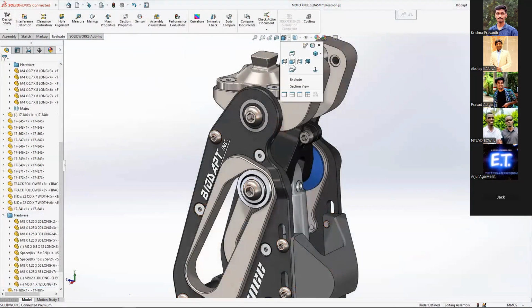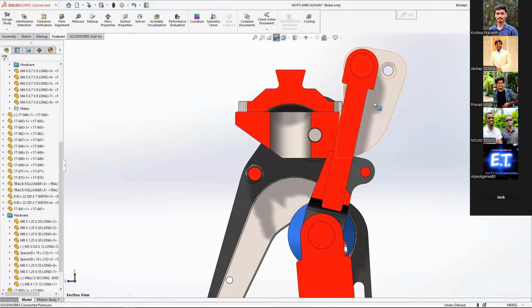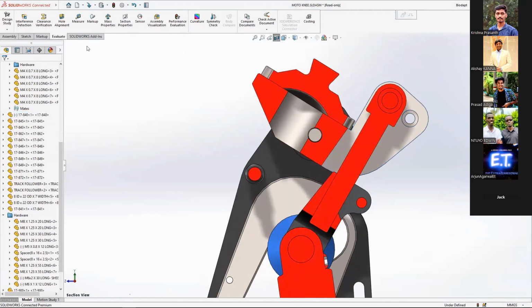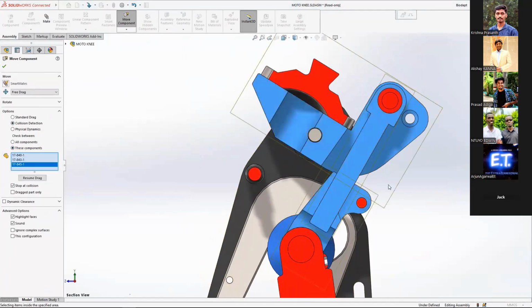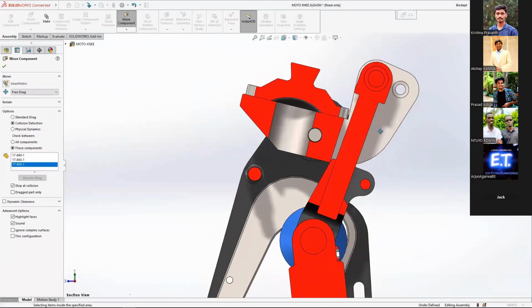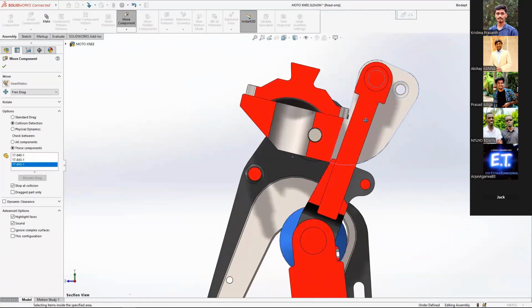So if you remember back to the post in the community, one of the engineers is asked to perform interference and collision detection. One of the great capabilities in SolidWorks is interference detection, or in this case, collision detection. Here the engineer does some real-time collision detection by simply moving some of the parts around on the screen, so he can see it stops at the collision.